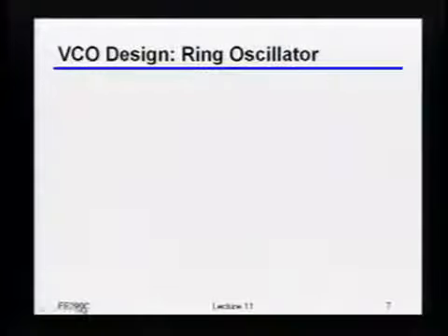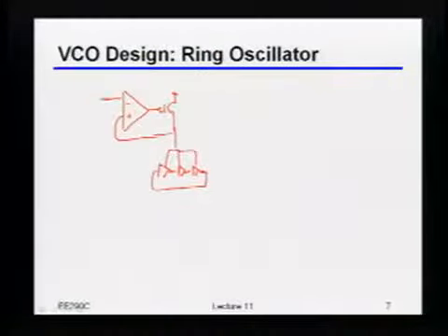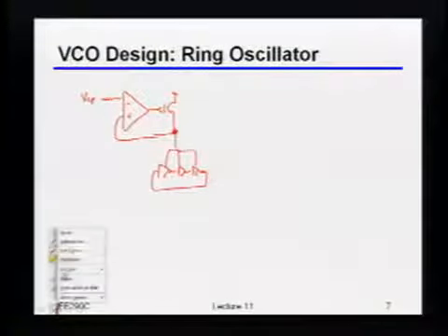But it turns out that in a lot of contexts, and for reasons that I'll explain shortly, one of the fairly popular architectures these days is to basically just use a supply regulator to set the supply voltage of some ring oscillator. Then just use that ring oscillator to act as your frequency source. So this would be coming from the charge pump voltage. This would be your internal power supply voltage. And then at least conceptually, this would be the oscillator, and the output would be right here.